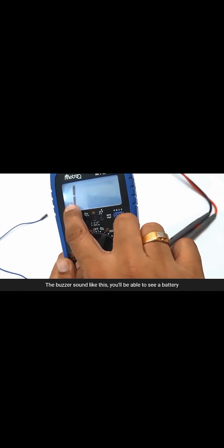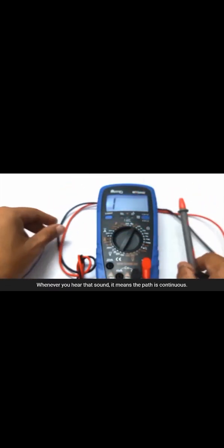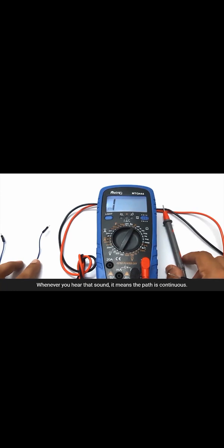You'll be able to see a battery shine. Now take the two probes, connect the two probes to the two terminals of the circuit or a wire. So you can hear a sound. Whenever you hear that sound, it means the path is continuous. If you won't hear the sound, it means the path is not continuous.